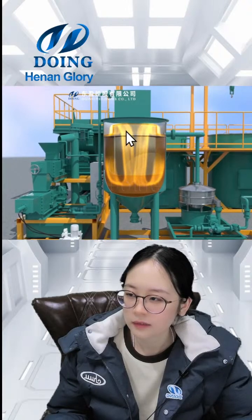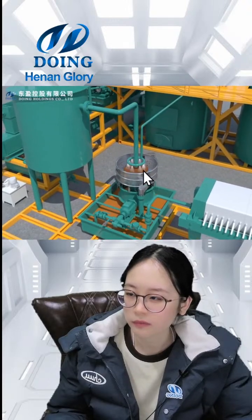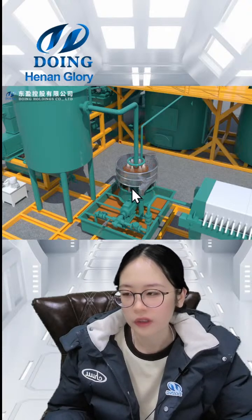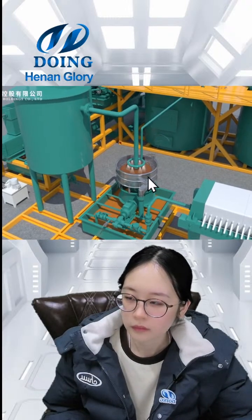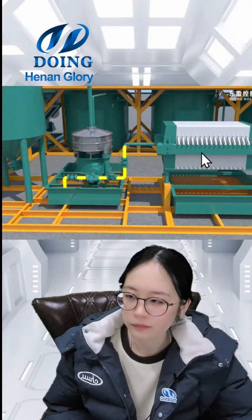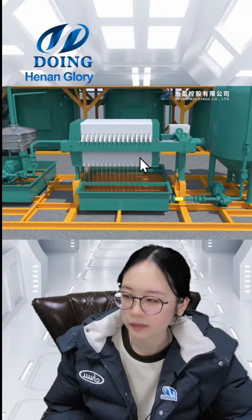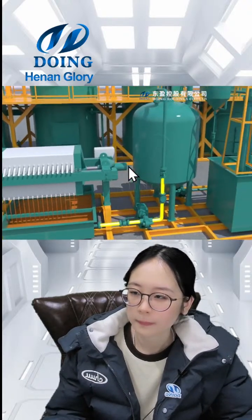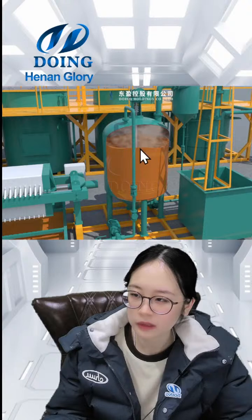Look at this tank. And then it goes to the vibration sieve. At the vibration sieve, hot water comes out. Hot water can keep the oil running. And then the oil goes to the filter press. The filter press can press out the oil, and the impurities as well. And this tank is for separating the water and oil.